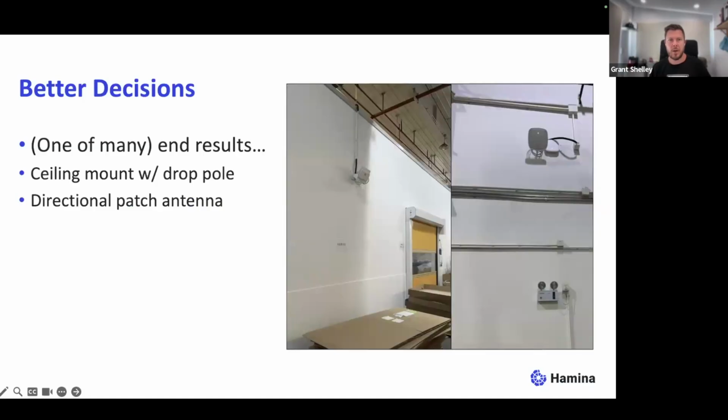I guess the other one, again coming back to the wall mount, is probably using the directional patch antenna here, which, do you want to take us through? We've got a couple of options on this one. On the left-hand side, we had, I think it was a 2566 P4W from memory, a Cisco antenna, a nice 120-degree angled patch antenna, just to give coverage down below because there were restrictions on placing access points within the ceiling. So we utilized this to be able to service it, and we couldn't actually get scissor lifts in this facility.